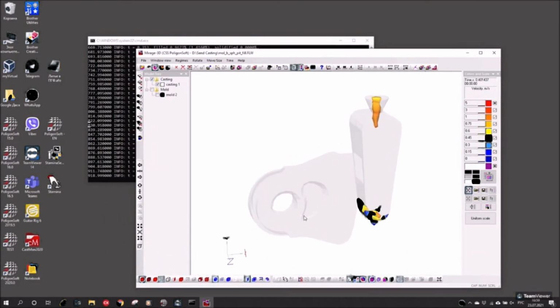We can see velocities, and here we see some gradient colors. If we turn it off, we see colors as here. There are 10 colors on a scale, and I can make a double click with my left mouse button to see the velocity value everywhere. A lot of points. And with a double click of the right button, I will turn off points.